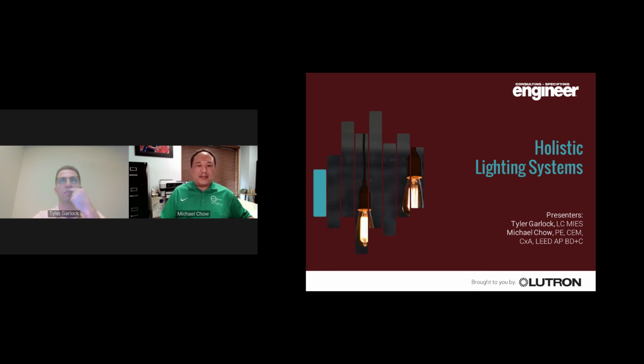Sure. So I think we went over some of the strategies during the presentation. Some of the ones I didn't cover are related to what's called bi-level control. So the energy code, whether it's IECC or ASHRAE 90.1, requires that instead of just an on-off, you have one more level. ASHRAE 90.1 requires between 30 and 70% of the lighting, and I believe IECC is 50%. So there's multiple ways to do that.